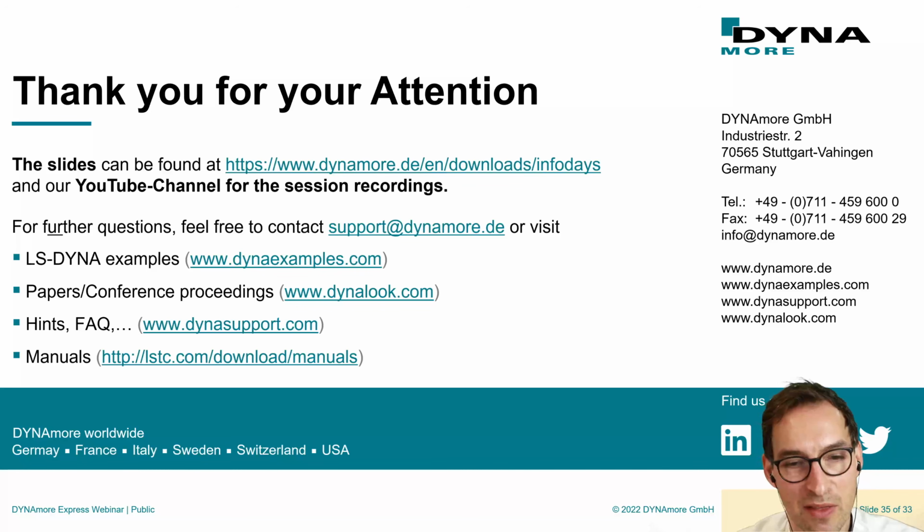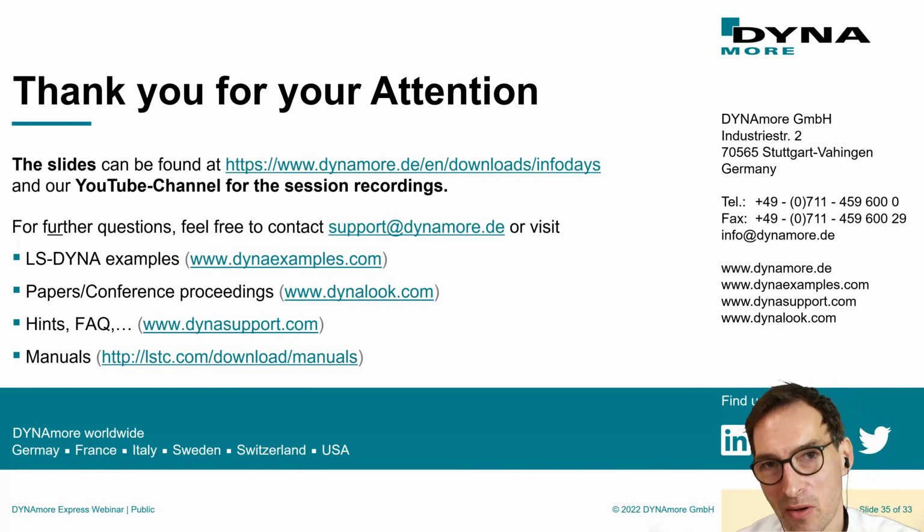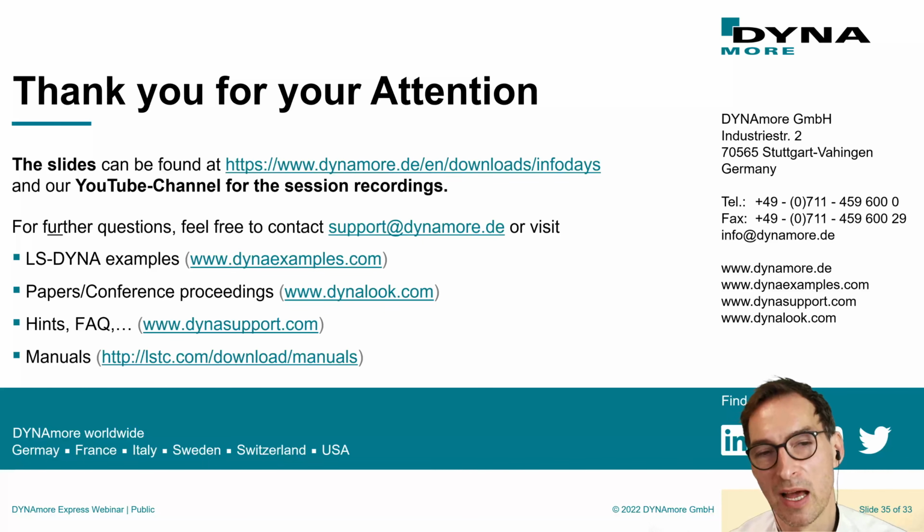Okay, there's a question. Which method is better suited to simulate pasty liquids, adhesives, ALE or SPH? Good question. Based on my experience, I had better experience with the ALE method, but I would say none of these is perfect. You can also try to use the ICFD solver with level sets. Basically, you have your Lagrangian structure, which is deforming the ICFD mesh, and then inside of the ICFD mesh, you're using level sets to compute a distribution of your pasty liquid, so to say. So far, I had the best experience with this one. So rather than using SPH or ALE, you can go with ICFD.